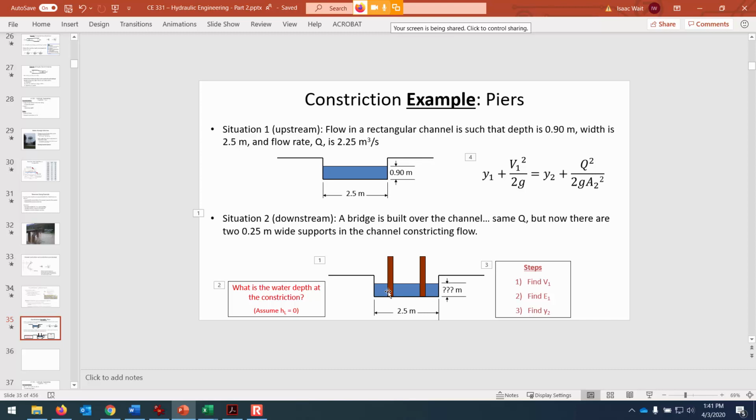And if you made those obstructions progressively wider and wider so that it obstructs the flow and causes pooling upstream, then yes, the water depth would increase upstream of the obstruction if we made these too wide. But these, we haven't gone beyond the maximum flow that can be accommodated without pooling upstream.